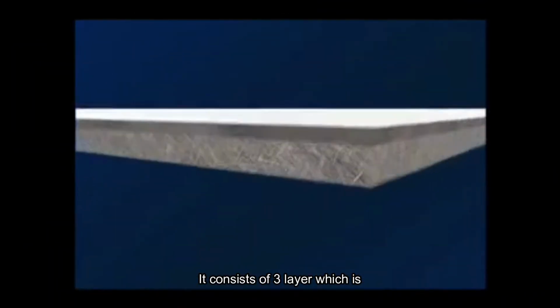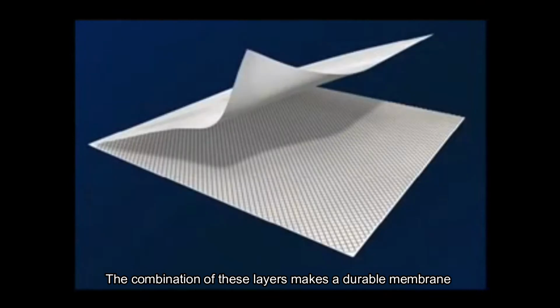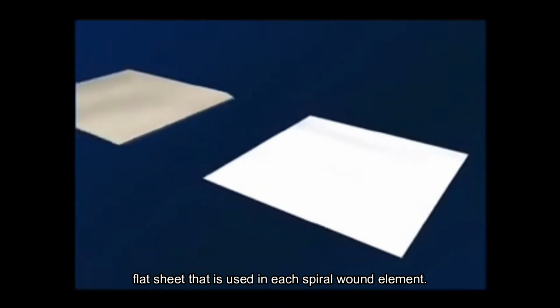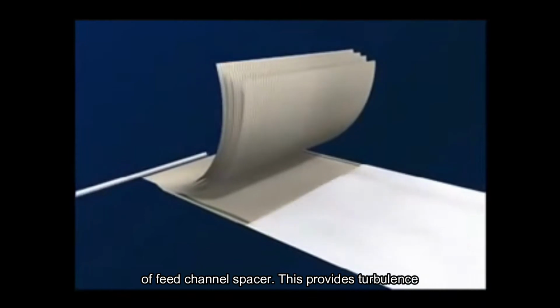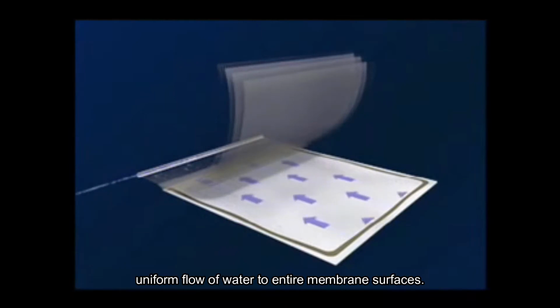It consists of 3 layers, which are a polyester base, a polysulfone layer, and lastly a polyamide layer. The combination of these layers makes a durable membrane flat sheet that is used in each spiral wound element. The membrane flat sheet is then combined with a sheet of feed channel spacer. This provides turbulence and creates space between membranes to allow uniform flow of water to the entire membrane surfaces.